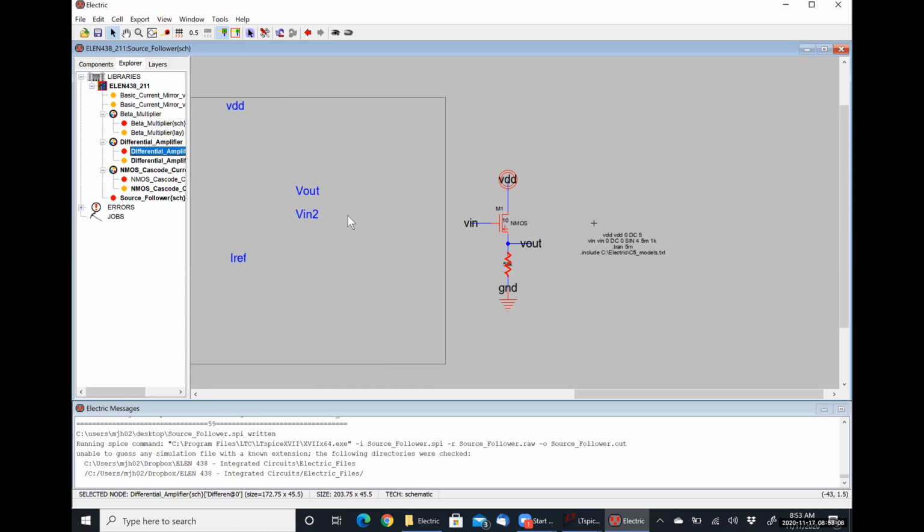This output buffer here is trying to carry that signal over, but we're connecting the output of our differential pair to the infinite input impedance or thereabout of our source follower amplifier, so that we'll get the same output voltage, but we could load it with something that wouldn't short the output to ground.